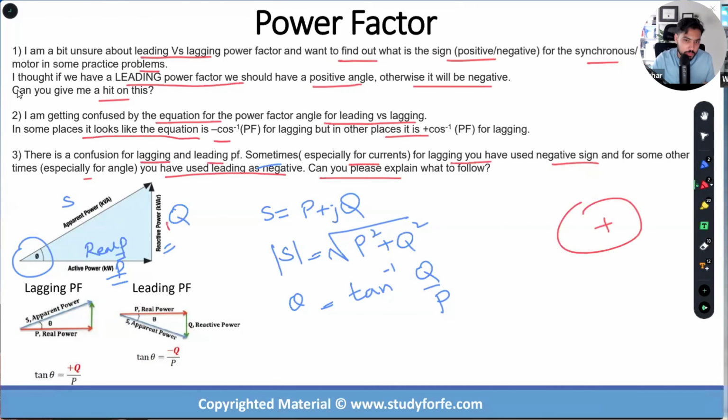So when Q is positive, it means that the load is inductive in nature or has some inductive component to it. Okay, is that clear? If you have a perpendicular, big or small, in the positive x y-axis direction, it means that there is a Q, big or small. Since this is positive, this is an inductor.